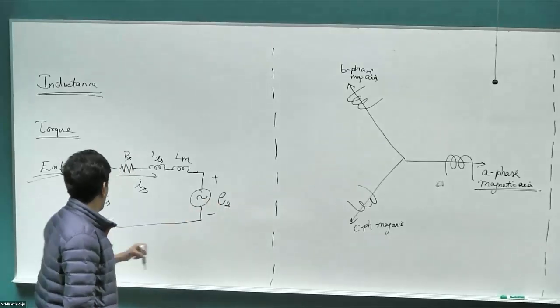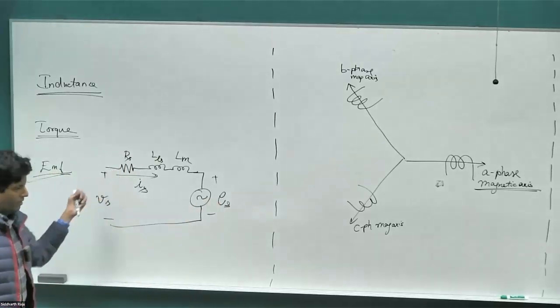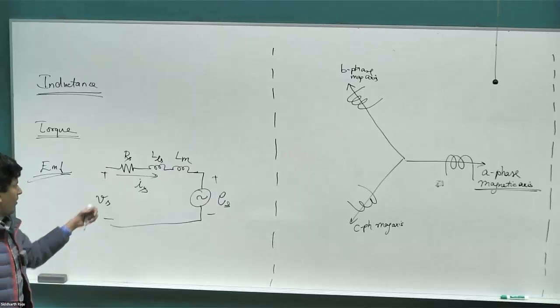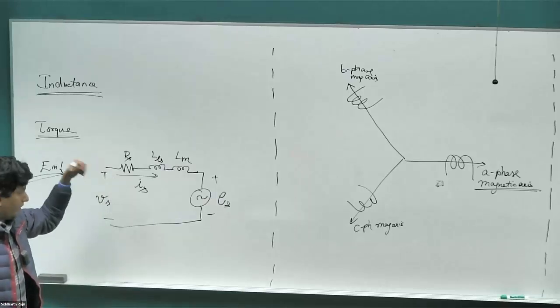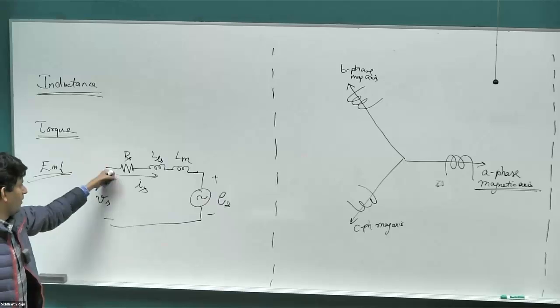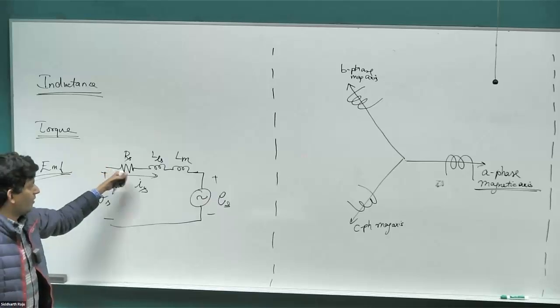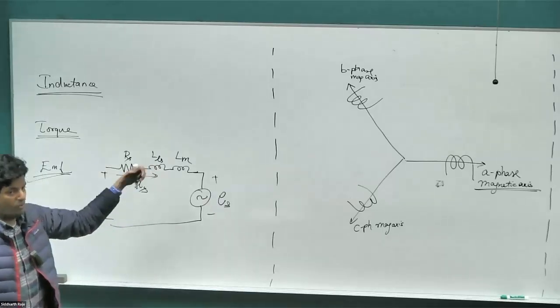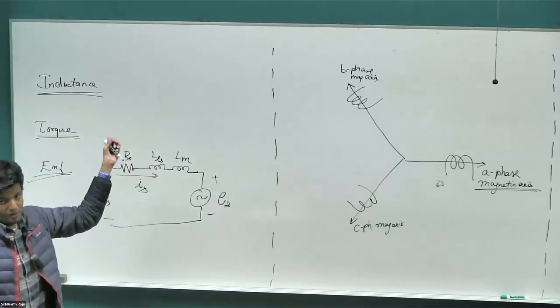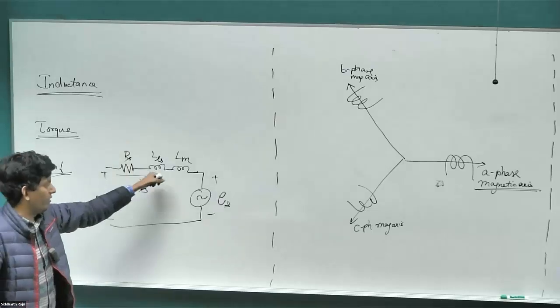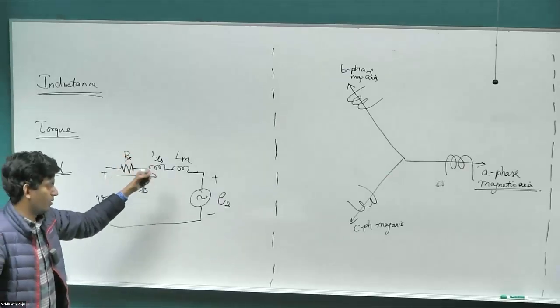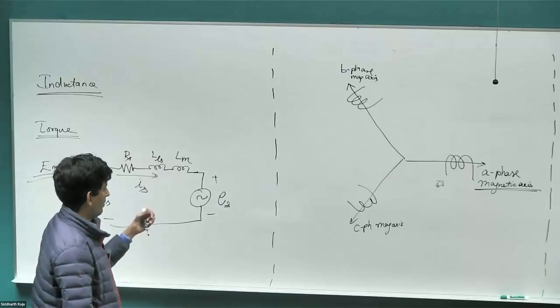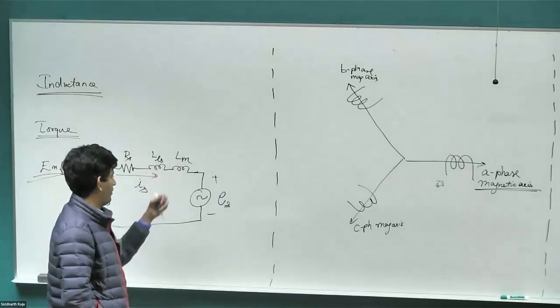So the resistance part is pretty straightforward. You have 3 sets of windings, you pass some current. You have some conductor wound on some core, so it's going to have its own resistance. And since it's a bunch of coil wound on an iron core, it's going to have its own inductance. That inductance is what created all the magnetic field in the air gap that we analyzed. Right now, we are going to try and get an expression for the inductance so that we can put it in a circuit form, whatever we have as just magnetics, the magnetic field in the air gap.